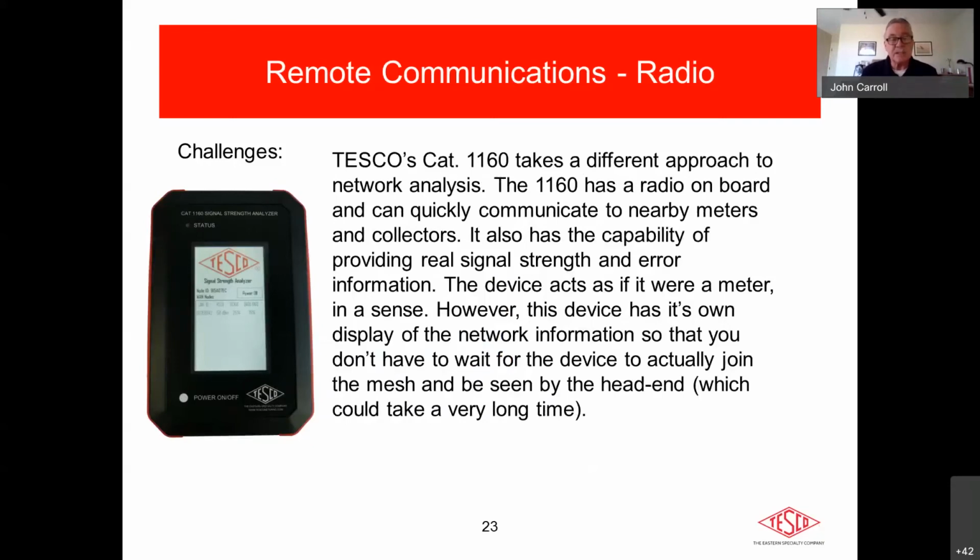So there was a big efficiency saving in it. However, it was generating a significant amount of harmonic content. It was so close to the meter that it was basically interfering with it, and it was preventing the read. So we did some studies, we got some information. If I remember, it was in the kilohertz region. I can't remember the exact number. I'd like to say it was like the 27th or 29th harmonic, which normally is insignificant. But in this case, that was the frequency that was interfering.